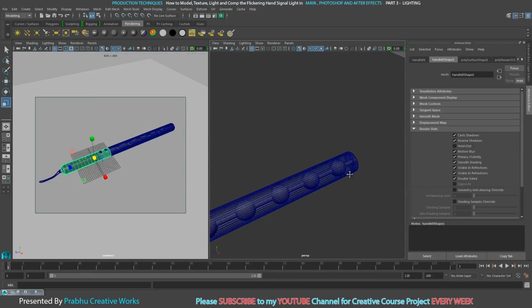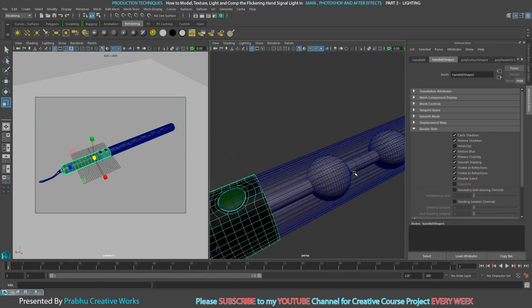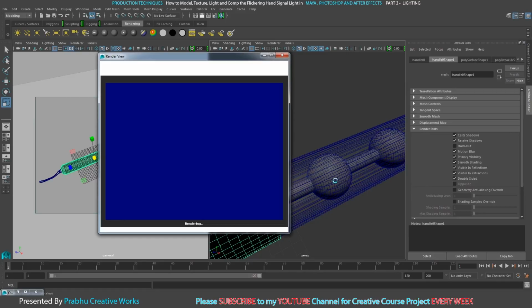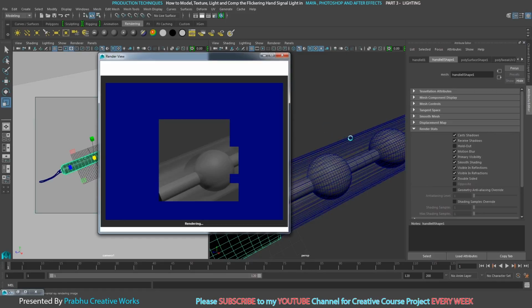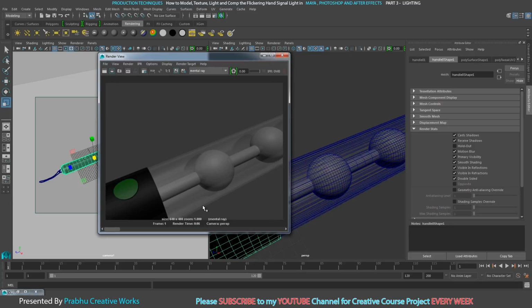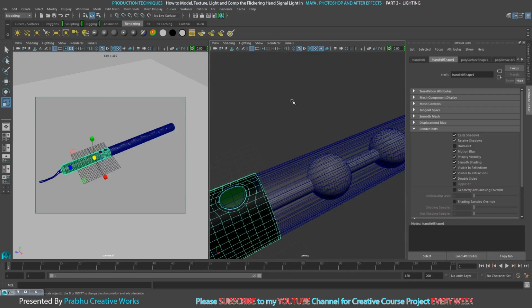So before that, see here, when I go closer over here, click this view and click the render button. So you will see what happened here in perspective. In this case it doesn't look like a glass material, because we have not enabled the ray tracing option. So if you have any glass material, you definitely want to turn on ray tracing for that material. So I will close my view.